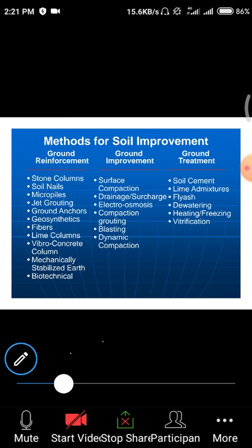That means if we use lime in a particular soil strata, the structural properties of the soil will increase, as it reacts with the surrounding particles present in the soil, so the total densification and strengthening occurs due to lime utilization in construction works below the ground level, not above the ground level.